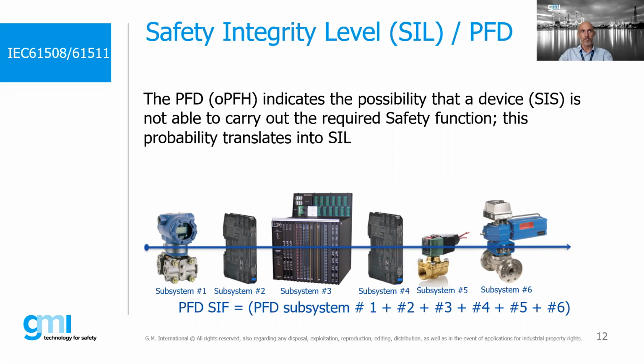So as you see, maybe you are aware of the PFD, probability of failure on demand, which is a really big part of the SIL level. The PFD indicates the possibility that a device is not able to carry out the correct safety function. So it's a very, very important parameter. And of course, if you have a SIF, a loop, all the parts that belong to the group have to have PFD available.